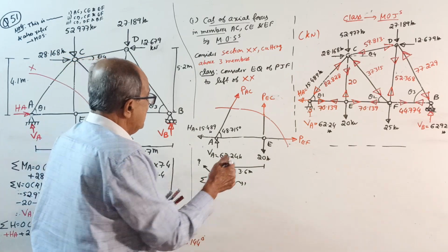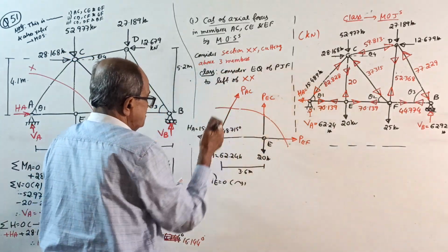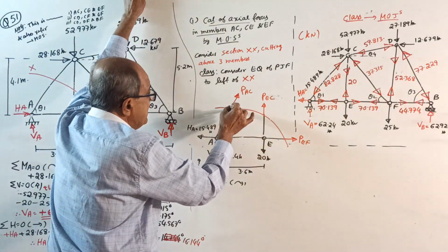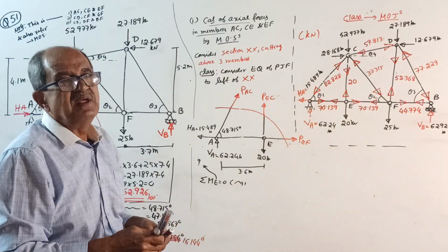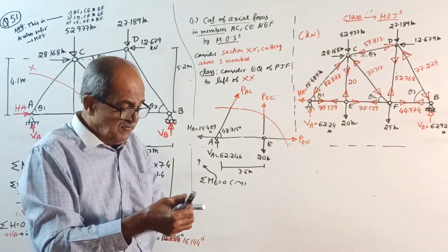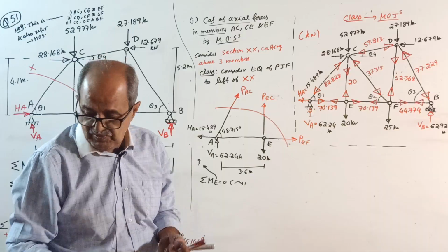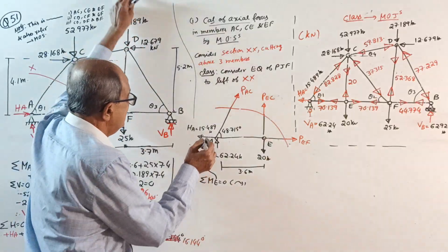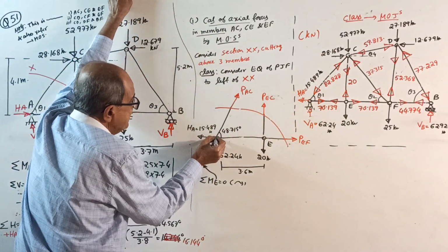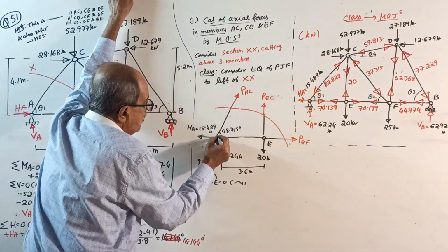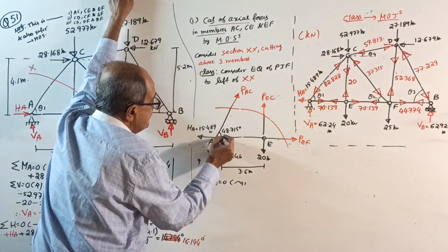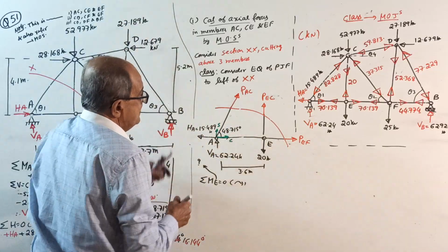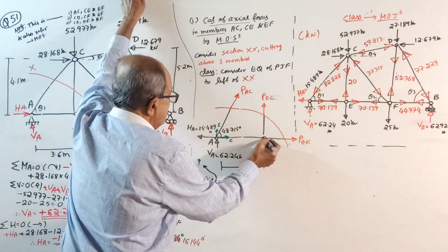Again, see here, this is an inclined force. So again I told you, you require a perpendicular. But no, leave it. Those who can, I'll tell you once again later how to get the perpendicular. The best option is: this force is passing here. For this force, one horizontal component with cos, one vertical component with sine. Make a note here.